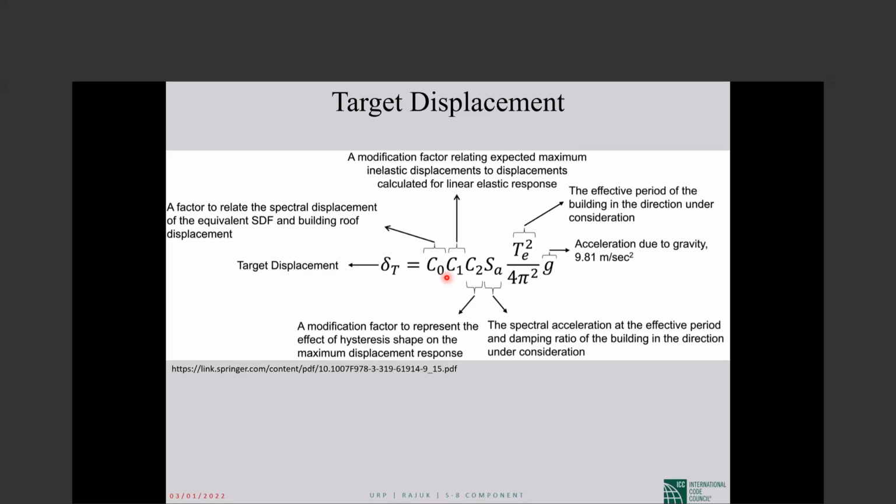If the drift increases from story 1 to the top, it is bending. If it decreases, it is shear. Then we can use those tables and find C0.